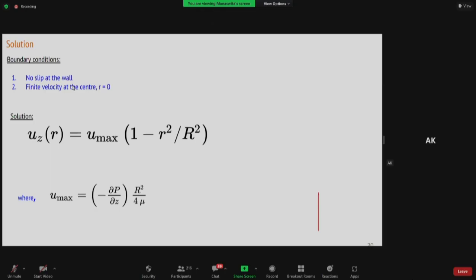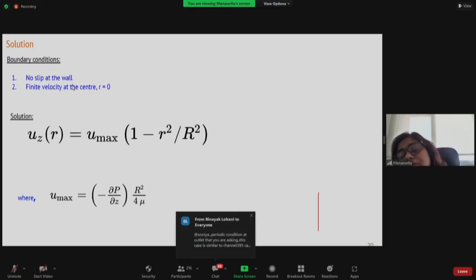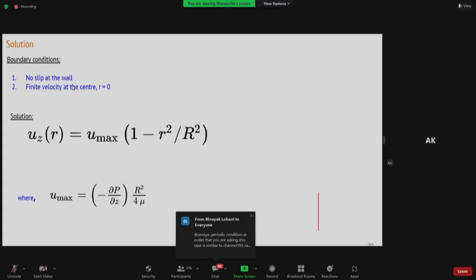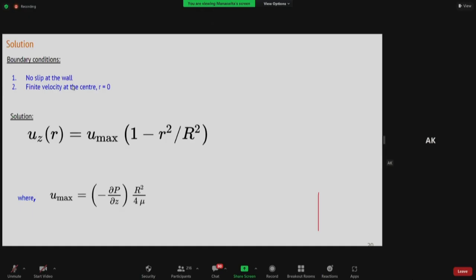If you define both pressure and velocity at both inlet and outlet, it is going to be over specification. What I meant was, at the inlet you say P is equal to the inlet pressure, and at the outlet you specify the gradient delta P is equal to 0. Like partial P partial Z is equal to 0. Just saying zero gradient at the outlet.